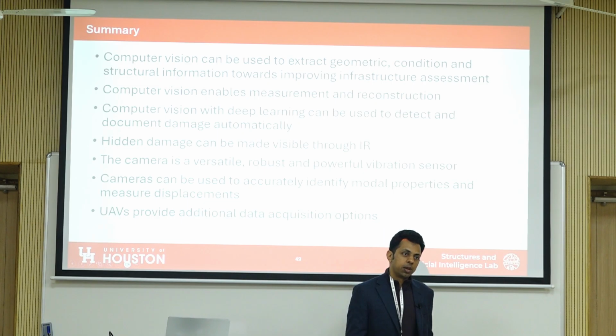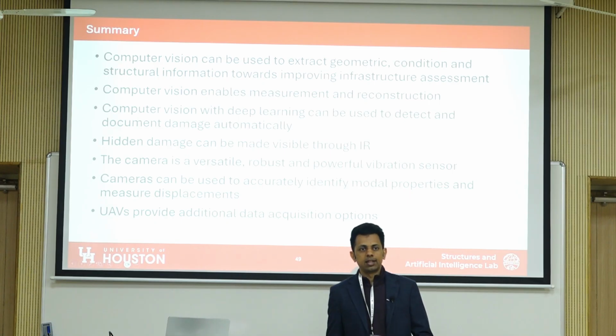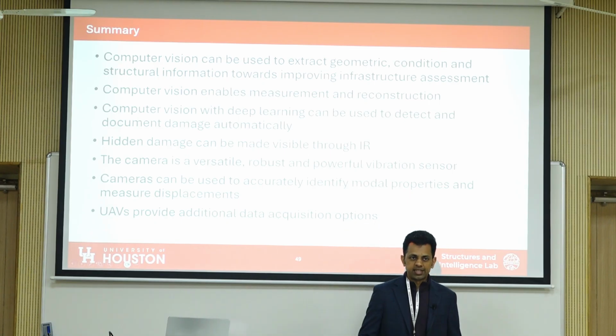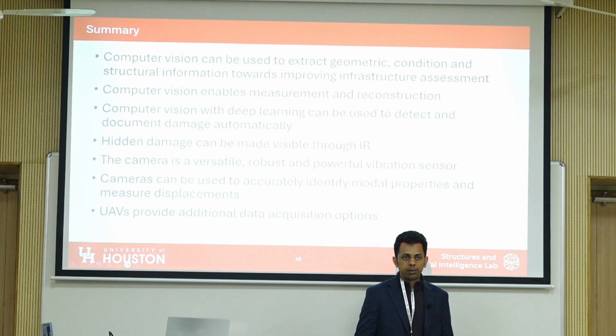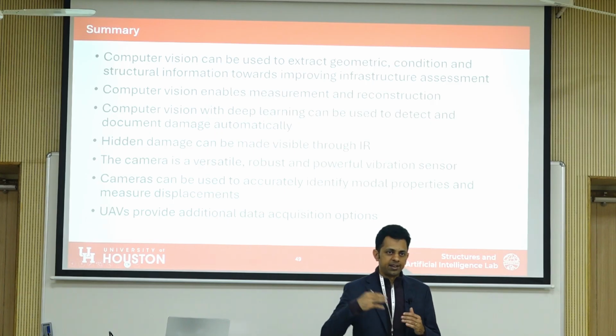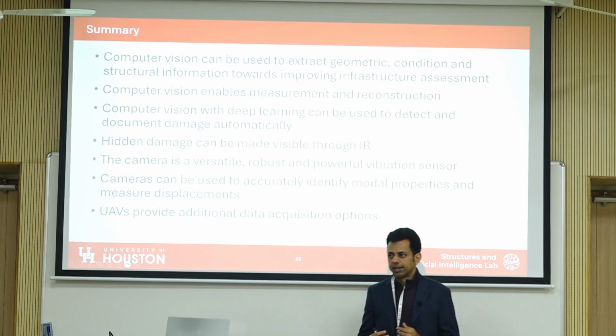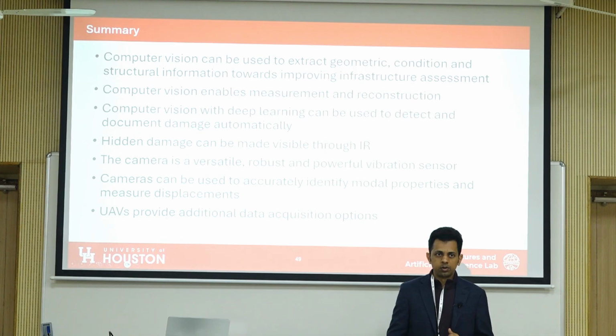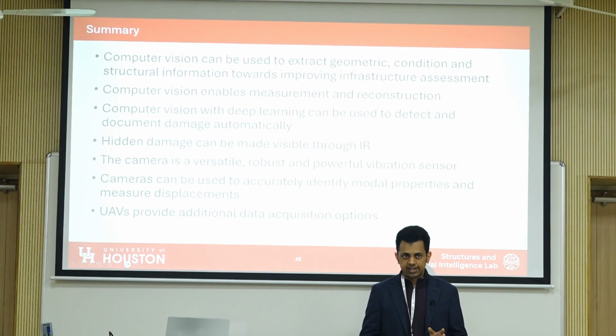And also, if you're doing public assets, then the Department of Transportation also has rules that you need to follow. For example, in Texas, if you're doing a bridge, you must fly at least 50 feet above a bridge if there's traffic on the bridge, because they want to have a factor of safety above the height of the tallest truck that might be on that bridge. And so I'm sure there are similar rules here in India. So there are all of those constraints.